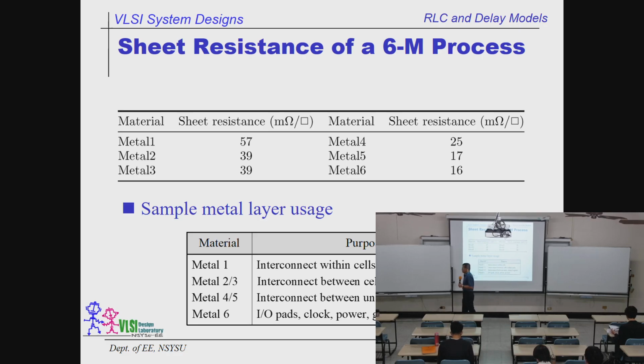Rule number two is that they always emphasize one thing. They have to plug in all the parasitics, including the capacitance, resistance, and even conductance, in the pre-layout simulation before they do the layout. That's how they do it, because that will save a lot of pain. When you find out the numbers you get before and after the layout simulation are so different, you have big trouble explaining to your supervisors, managers, and colleagues what the hell is going on.